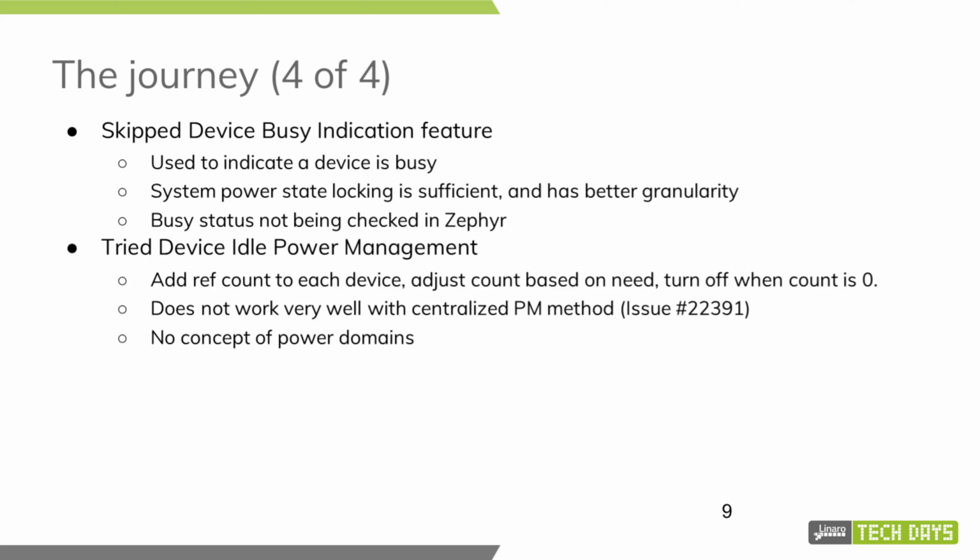And also it doesn't have the concept of power domains. And sorry, I forgot to define power domains earlier, but power domains are basically partitioning of the device that can be turned on and off as a whole together. And because it doesn't have this concept, it was better to make use of the TI Power Manager instead.